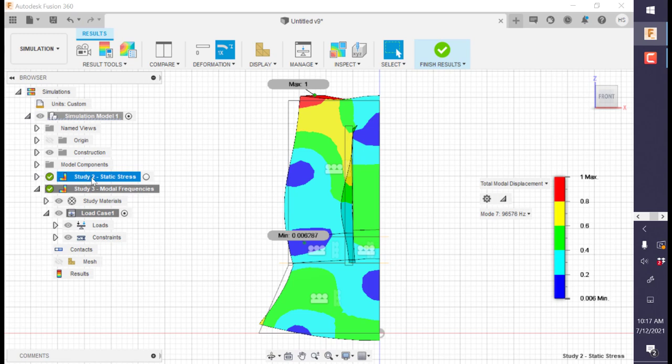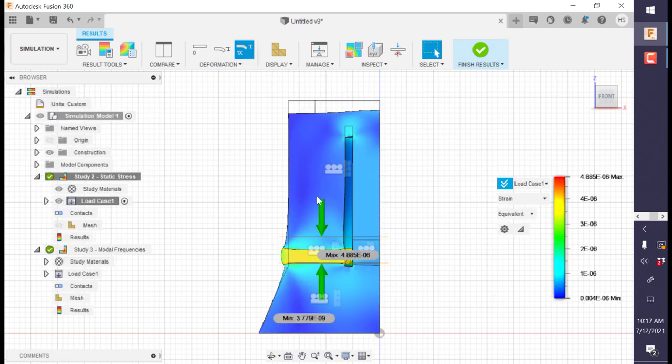The other thing we can look at in simulation is off resonance displacement and actuation. Here I'm using static stress. The specific program doesn't have a frequency response analysis. However, driving at low frequency will result in the same displacement levels as driving in static conditions.